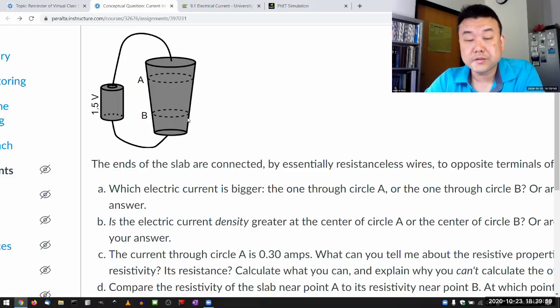So that when you apply Ohm's law over that slice of the conductor, the current ends up being the same, because the resistance of this slice is lower, but the voltage difference across the slice is also lower compared to the resistance here and the voltage difference across that slice.